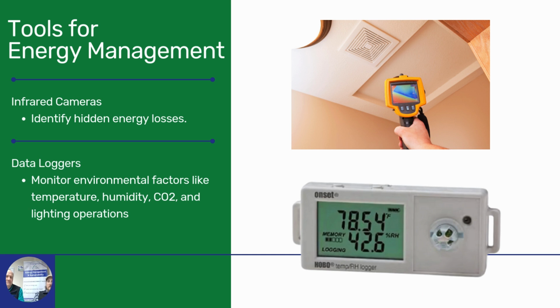So when we get hired to come in and walk a building and make some observations, sometimes we're making those based on our experience, but then other times, as we get deeper into more progressive levels of energy audit, we're starting to use some tools to give us additional data, not just what's on the utility bill, but what's behind the walls? How much insulation is there? What's above the ceiling? How can we look at the outside of the building and tell, is there actually any heat coming out?